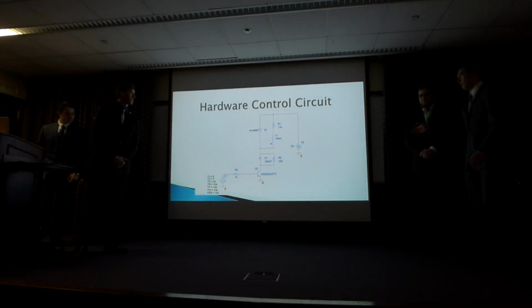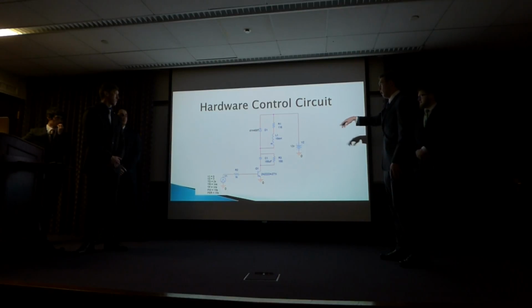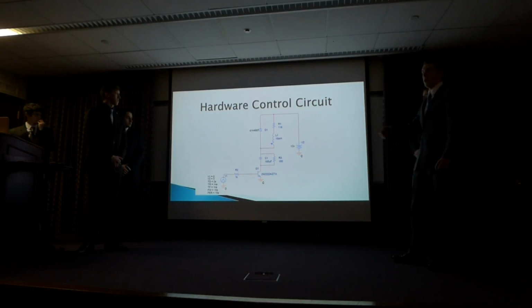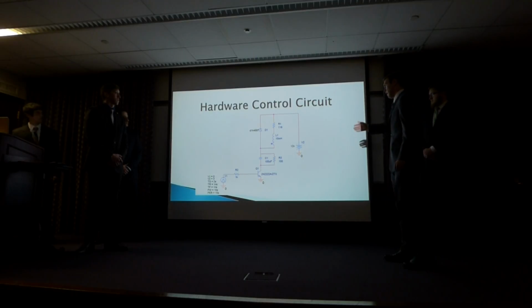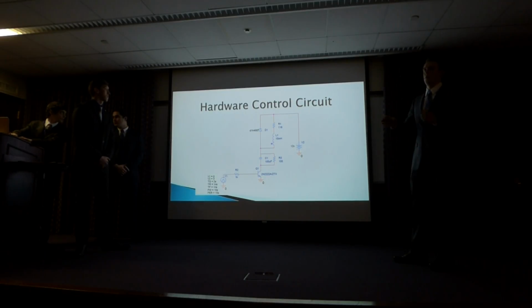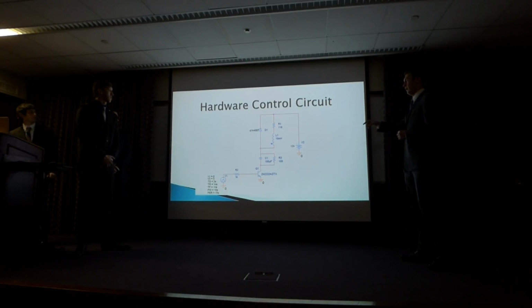So this is our hardware control circuit. Our solenoid valve is actually modeled by R1 and L1. Our solenoid valve actually needs 12 volts to operate properly, but we can only achieve 3 volts out of a driving microcontroller. So we built up this system. The capacitor C1 and R3 also work to lower the energy that's going to be dissipated across our transistor Q1 when it turns off.